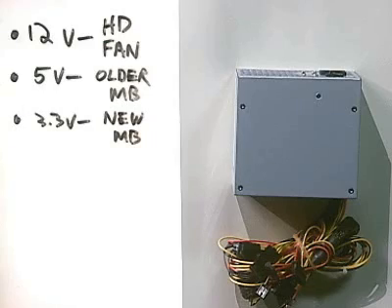In this lesson, we're going to talk about power supplies. Now, the power supply plays a crucial role in your PC system. Its job is to provide electrical power to every single component in your computer system. What it does is convert 120 volt AC current from a wall outlet into DC current that can be used by the PC system. And it actually converts that 120 volt current into 3 different DC voltage levels.